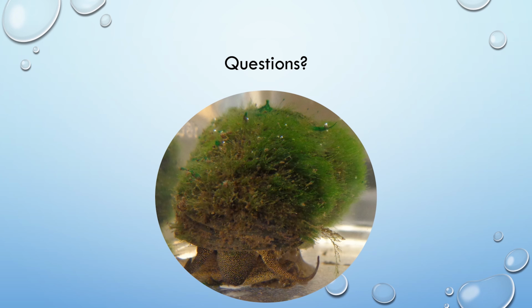Another question we have is, can you use a product in conjunction with ferric chloride for phosphorus? I'm not entirely certain about that, since ferric chloride's generally used on your effluent or to polish your effluent from the clarifier. I have heard reports of using a lanthanum product for it. I'm not too certain if that's a way you want to go. It is pretty expensive. But generally, those two should be able to be used together. You'll just possibly have excess ferric or lanthanum in your effluent.